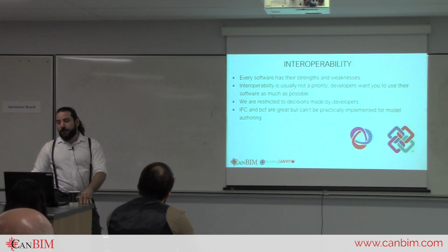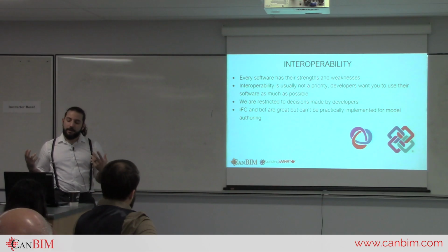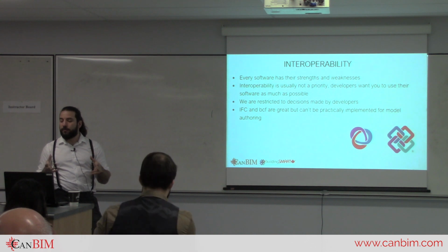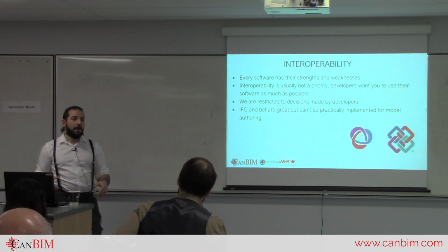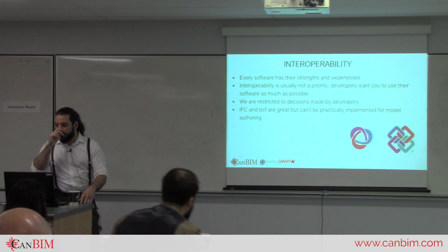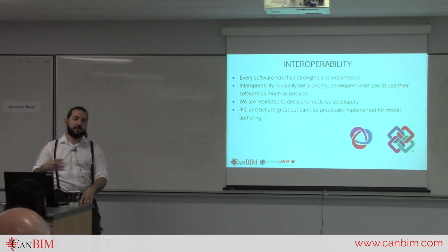So IFC and BCF are open standards. IFC is an open source model format. BCF is for coordinating between different software, so it's strictly a collaboration format. It just records the place, comments, and a picture of your issues, basically. This actually works fairly well.